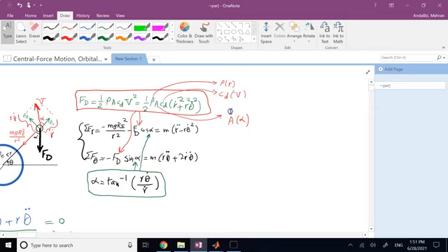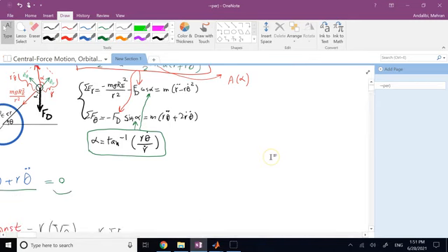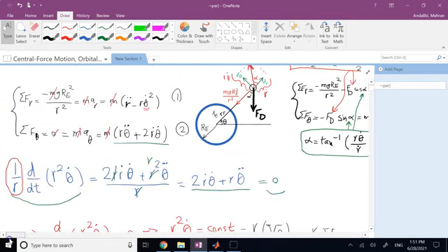A we might, yes, A is not that bad if you have the CAD model of our satellite, we can look at it at any angle and get A. CD, maybe we have some good results from wind tunnels at high speed. The hardest part, as I said, is rho, okay, for which we have to use a lookup table for different layers of atmosphere and for different conditions. So even solving this perfectly realistic with numerical solvers is a daunting task.